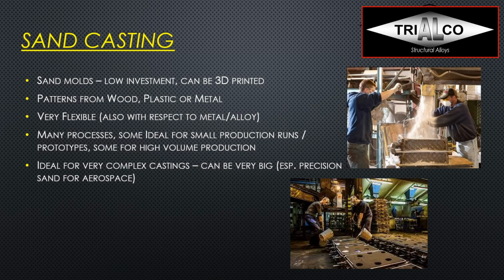But of course, we will always have a very long solidification time, so a very slow solidification. And usually we need thicker walls. You can fill thinner walls in sand casting if you do low pressure sand casting, but that is a rather rare process. And you will always have this pretty rough surface finish because it is as rough as your sand mold surface.